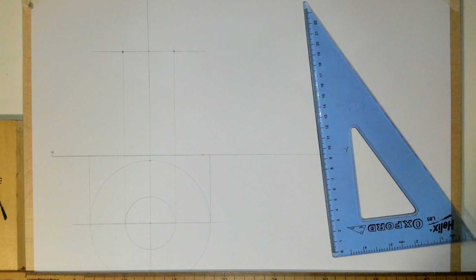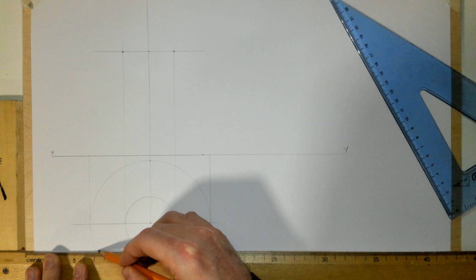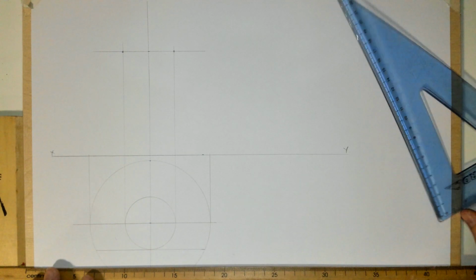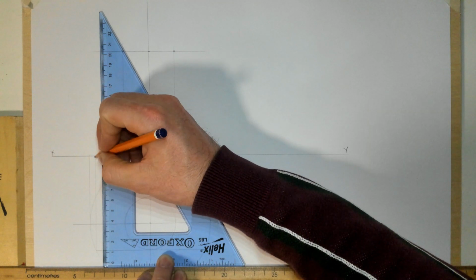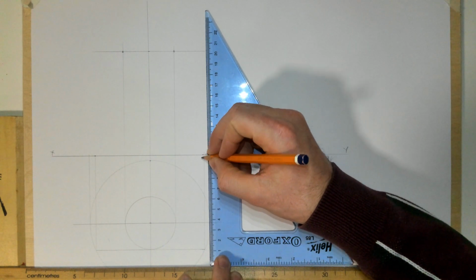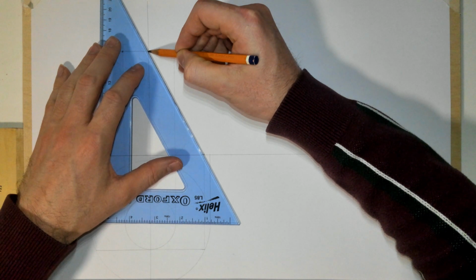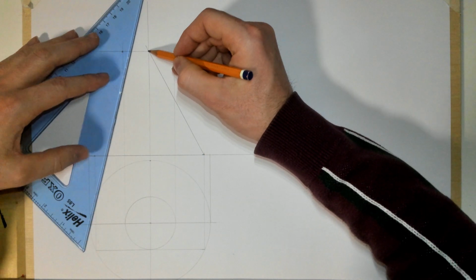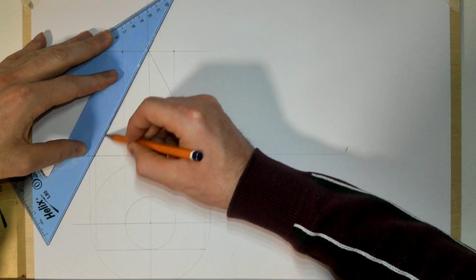Now, I'm going to use the asymptote method for this. So I'm going to draw a line tangent to the throat circle till it touches the outer edges of the big circle there. And then if we bring up the ends of the line where it touches the big circle, that gives me that point in front elevation and that point. And they're the 2 points needed now to draw in that X or that asymptote X in front elevation. Now it's not going to be an X this time, it's only going to be a V because it's only going to the center and we only need half. So we don't need to draw the full thing there.